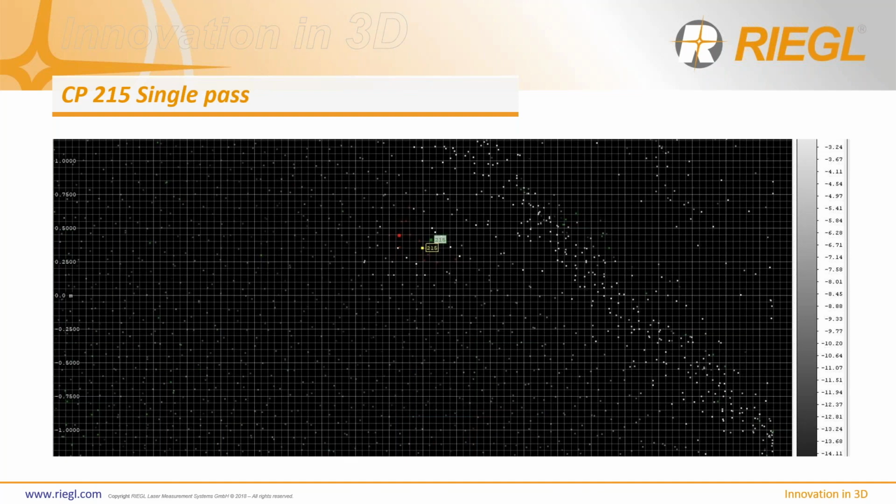So we check the green tag, and you can see right away that from this pass, which was on the main highway, this happens to be a control point on the shoulder that didn't really see enough of the data to make a determination of where it should be. Maybe I could squint at that and look at it at the right angle and really guess correctly where that center is, but my eyes aren't comfortable doing that typically. So that's another one I would remove because there's too much error in it.